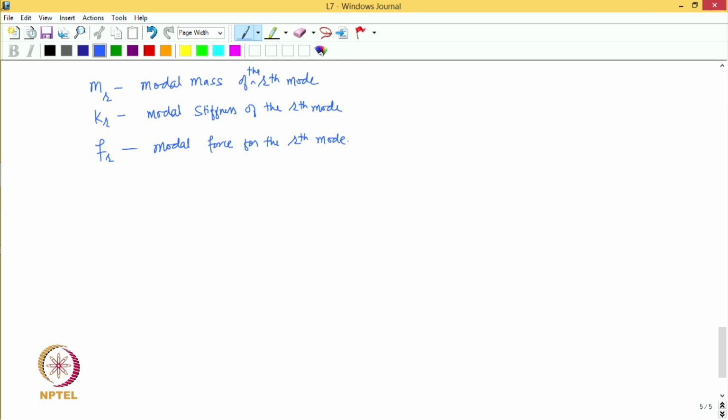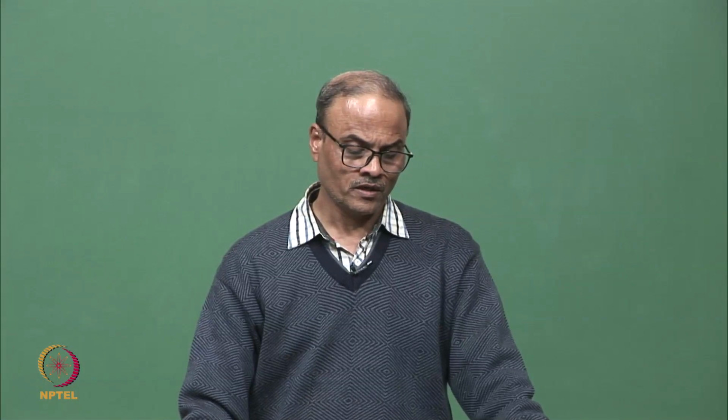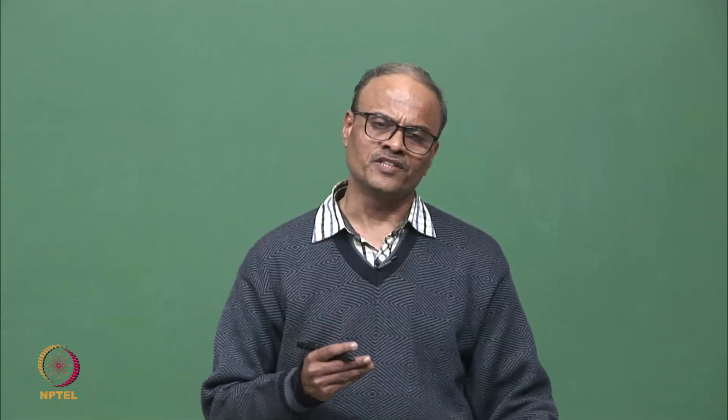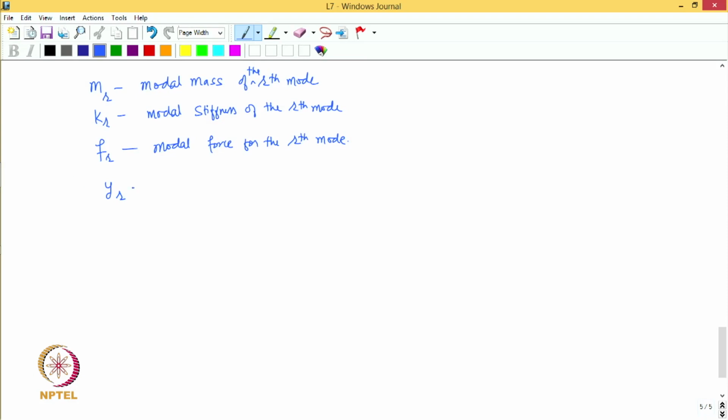So, before we solve the Rth differential equation and other differential equations corresponding to all the modes, we can further give a physical interpretation to the responses we obtain from these differential equations. So, yr basically tells us the response in the Rth mode of vibration, and that is why this is referred to as modal response.